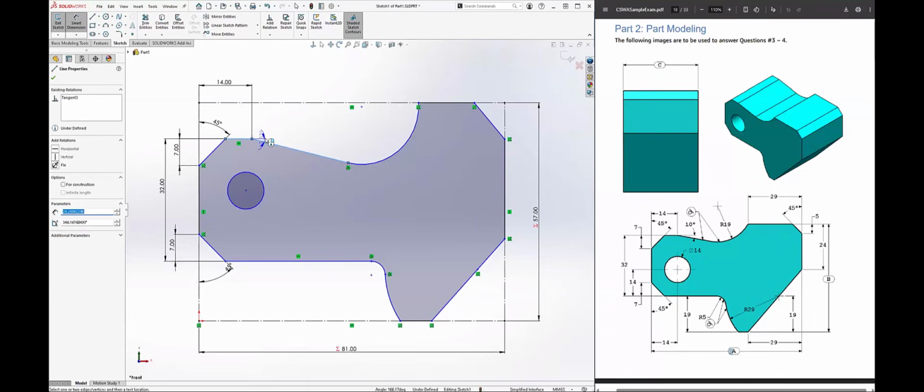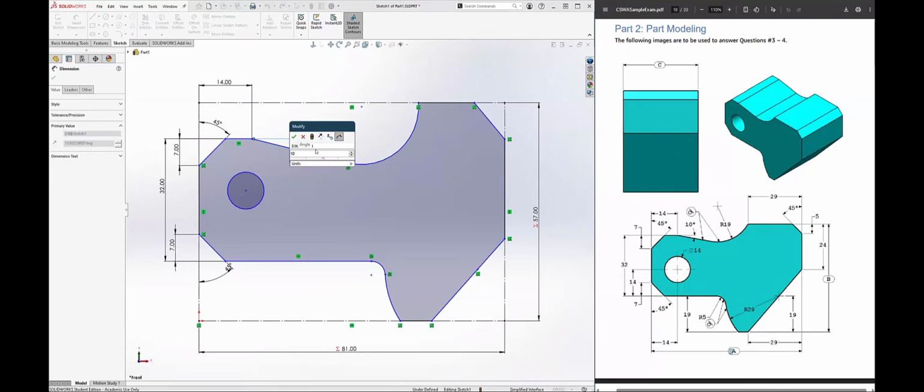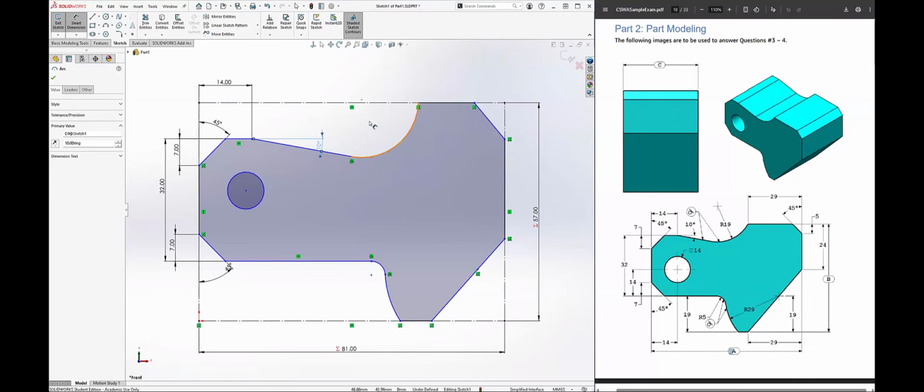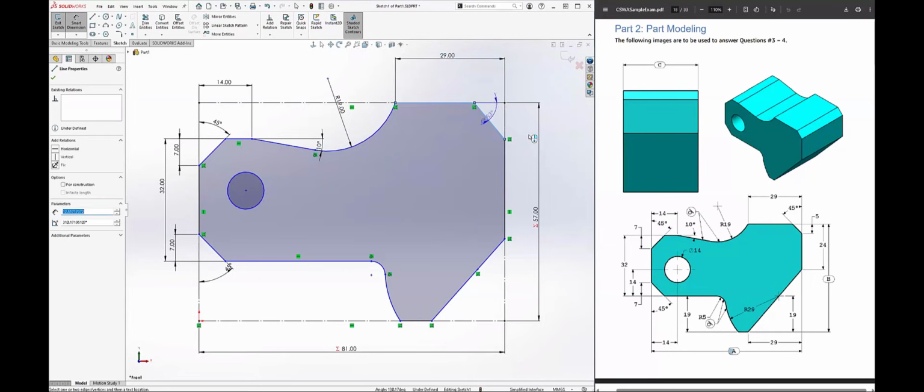If you want to get this acute angle here, the further you move out, the easier it is to select. We'll do arc here, 19. We'll do from this point to this edge of 29. Another 45 here. And because it's 45, we're not worried which one it is because it'll add up to 90 anyways.